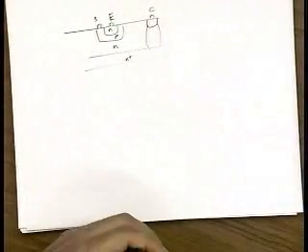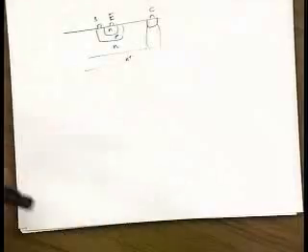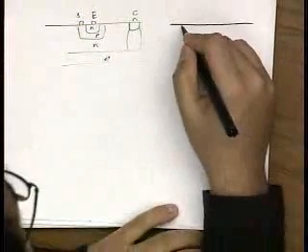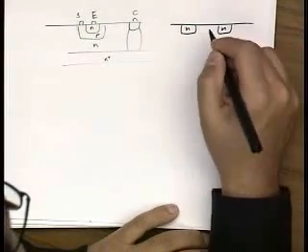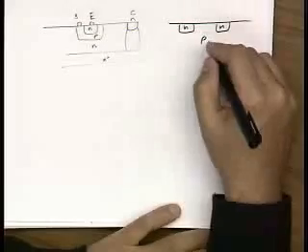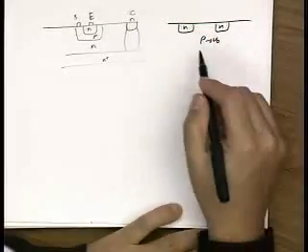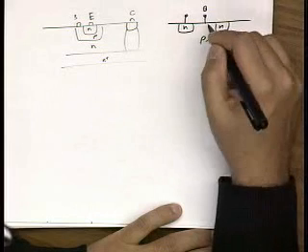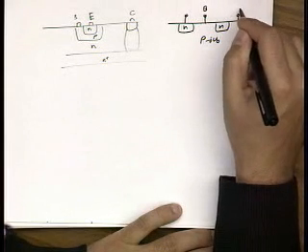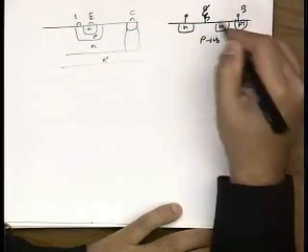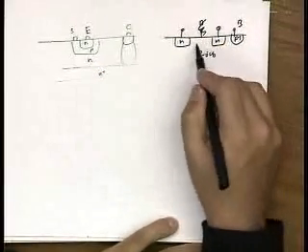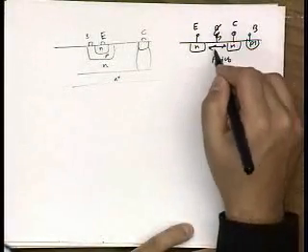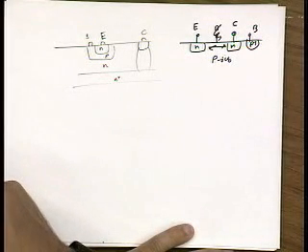On the other hand, if we look at traditional CMOS, let's say we wanted to do an NPN. Well, here's an N, here's an N, and here's the P, which is the substrate, right? Why isn't this a good transistor, right? So I could contact here. This could be like a P plus contact. Well, I could put it over here, let's say. I don't want to put it here because I want to make this channel length as small as possible. So this could be my emitter, this could be my collector, and this is my base. Why isn't this a good transistor?